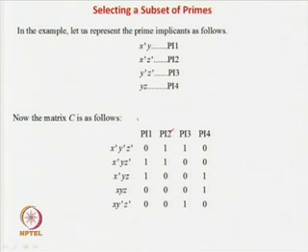In this case, these are the 3 prime implicants. We write x y', x' z', y' z', and y z. Why do you put a 1 over here? Because x' y' z' is x' z', so this minterm is included in prime implicant 2. Similarly, it is y' z', so even this term is included in prime implicant number 3, and so forth. But this one is not implicated with y z, so it is not included over here. You can easily find that out.